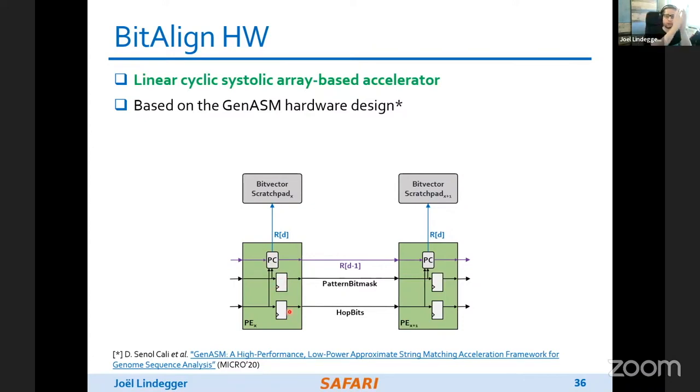So you compute a little bit, you pass on, and you always receive something from your direct neighbor. The key point is that this works really efficiently as long as the data that you need is always the data from your direct neighbor, to your left in this case. If this element only needs data that its neighbor just worked on in the last cycle, all is fine and dandy. It works highly efficiently.